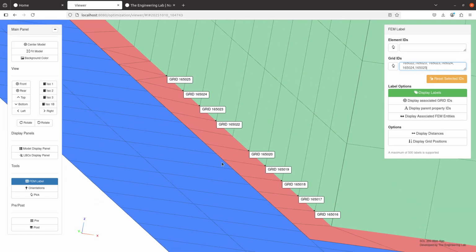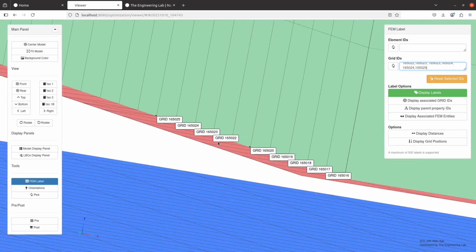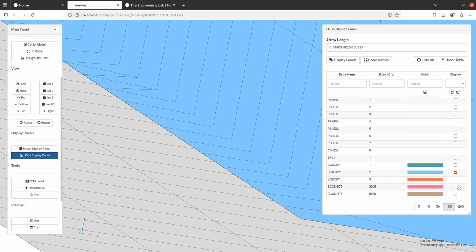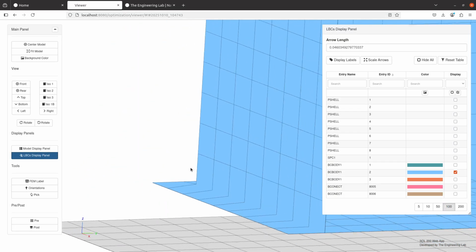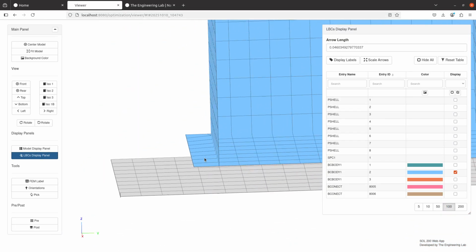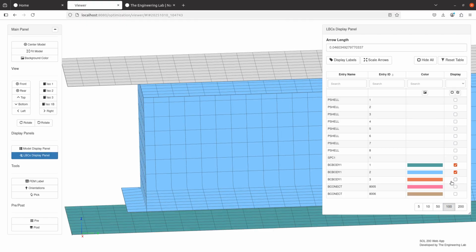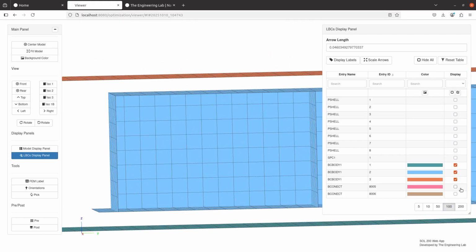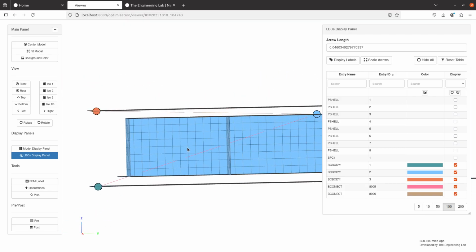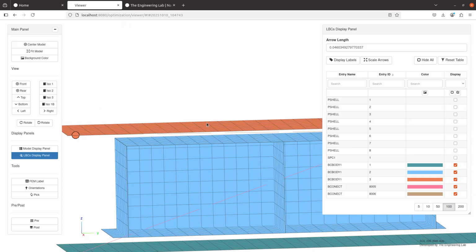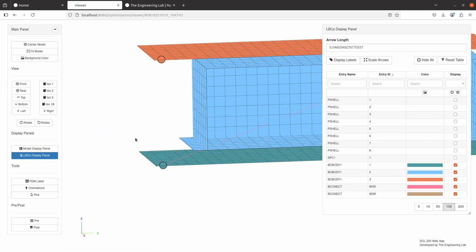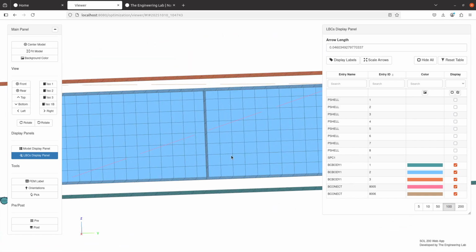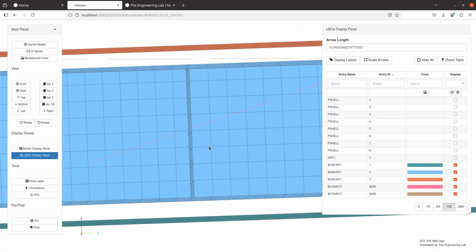one another. Here it's telling us that it might be better to separate this contact body. Right now this contact body is one single piece, and from that message it's suggesting that maybe we should break up these contact bodies. Right now we have 3 contact bodies defined and 2 contact pairs. So the contact pairs are represented by these spheres and these dotted lines. So this contact body on the top, it's allowed to contact this blue body. This contact body on the bottom, it's allowed to contact this blue body in the center.